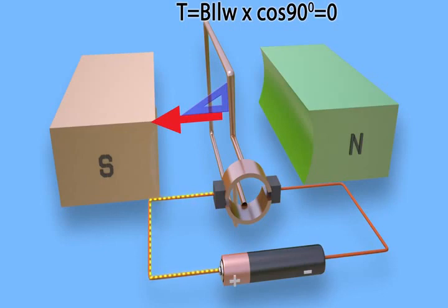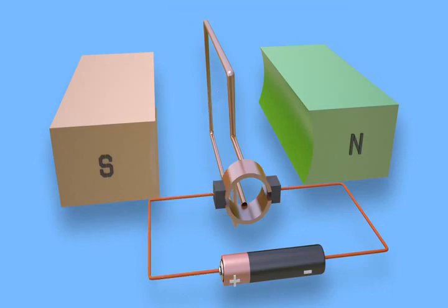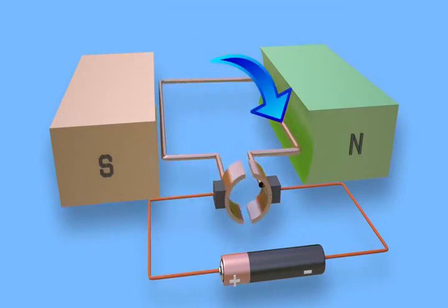At this position there is no current in the conductor because the turn's conductors and brushes rest between the two commutator segments. Hence, there is no force acting on the conductor, but due to moment of inertia, the turn continues to rotate and comes horizontal again.